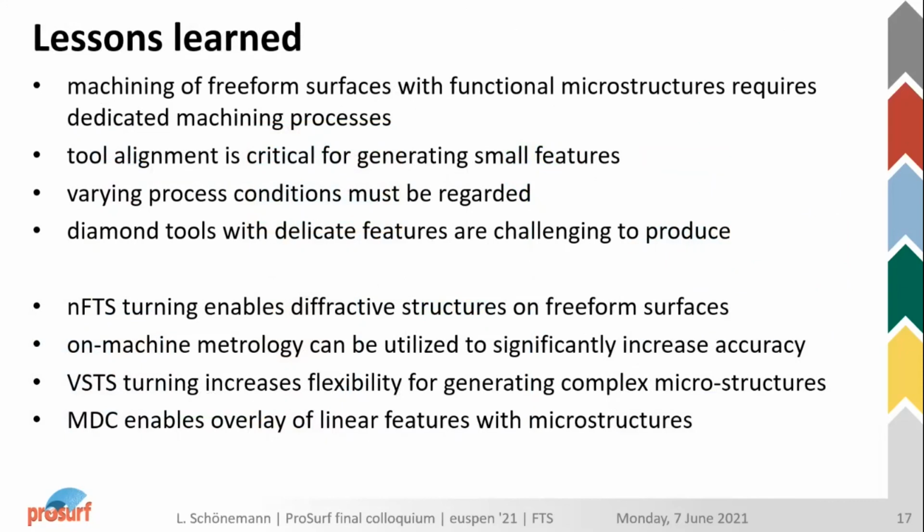We have considered the varying process loads in this case, and also looked at specifically designed diamond tools that aid in generating these kinds of microstructures in a Fast Tool Servo turning process. And we considered a lot of processes like Nano Fast Tool Servo turning, virtual spindle tool servo turning, and so on.